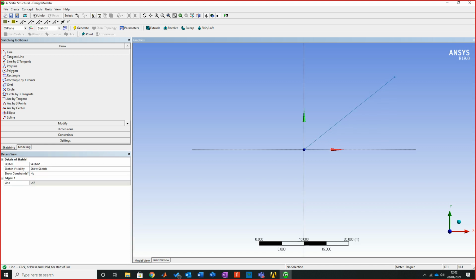draw a diagonal line. Then I'm going to come from this point here. See how the rectangles appeared on the end? Left click again, bring that all the way across. For those of you who have used Inventor, CATIA, SolidWorks, and anything like that, you will know that the systems often bring you up a vertical and a horizontal marker to tell you if the line's going to be marked out like that. You'll notice on here it's giving me a massive H. Massive H is the equivalent of what you get used to in the typical CAD system.